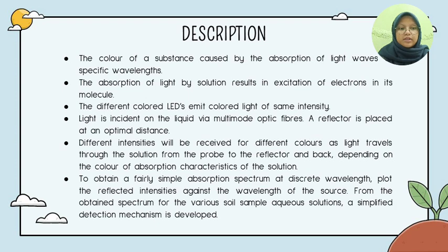The different color LED emit colored light of same intensity. Light is incident on the liquid via multimode optic fibers. A reflector is placed at an optimal distance. Different intensity will be received for different colors as light travels through the solution from the probe to the reflector and back, depending on the color of absorption characteristic of the solution.